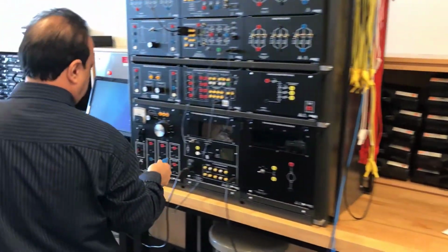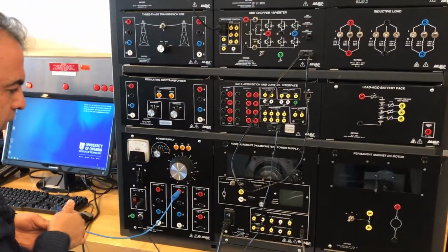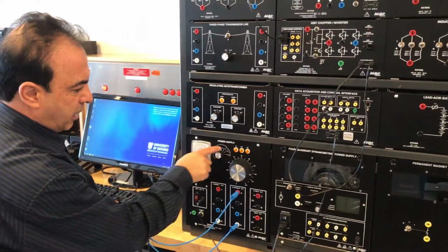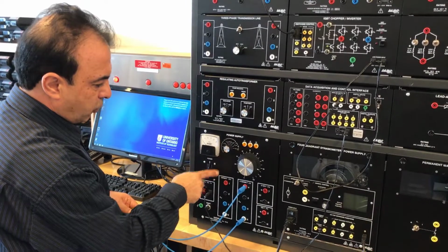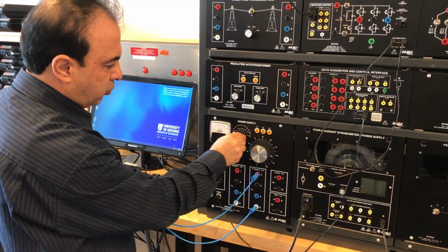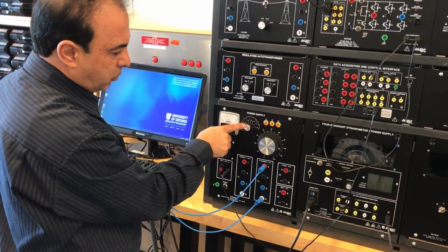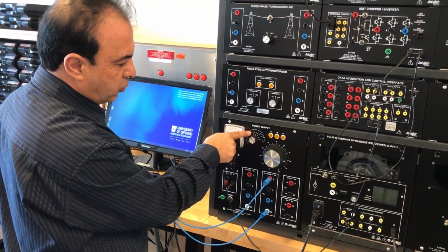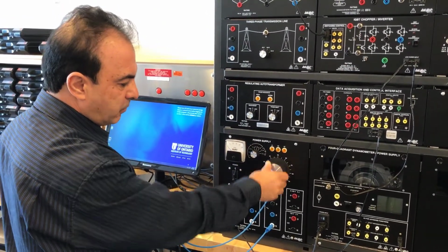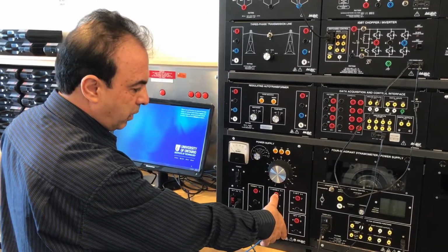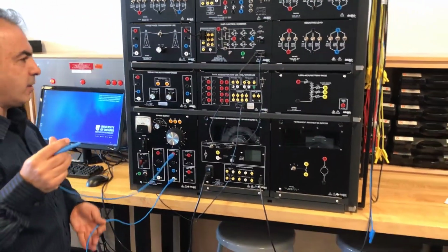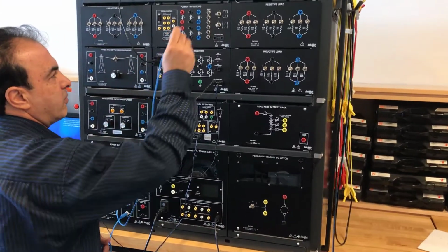So what I do, I connect one to number 4 and one to neutral here, and I have to make sure that I choose the selector so that it addresses 4 to neutral. This one, you see it's choosing the 4 to neutral. So this means that when I turn this knob, the voltage between these two is going to change. So I am going to connect this to start, let's say, with the resistive load.